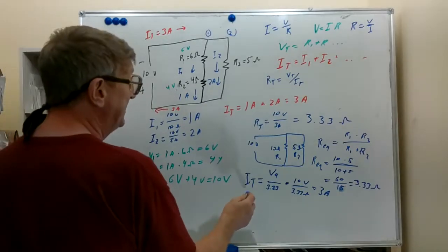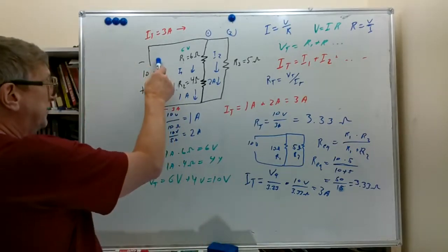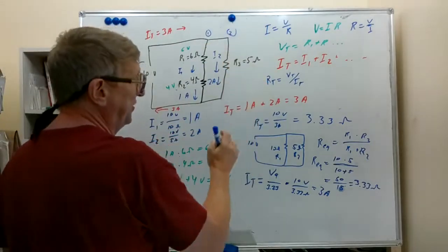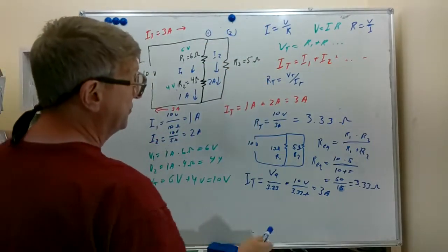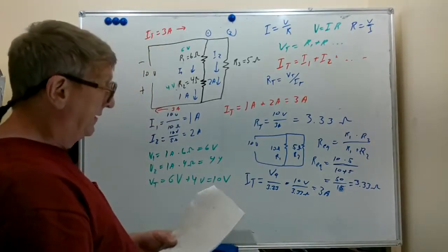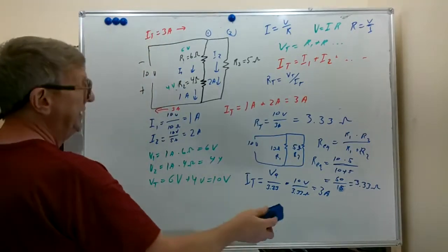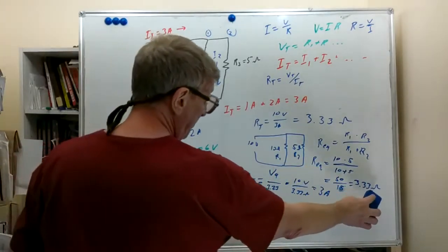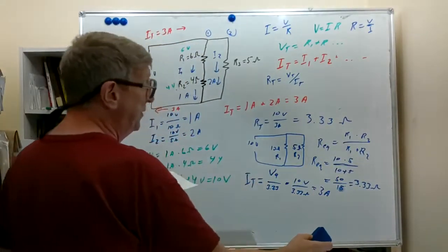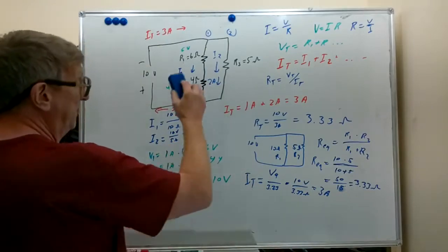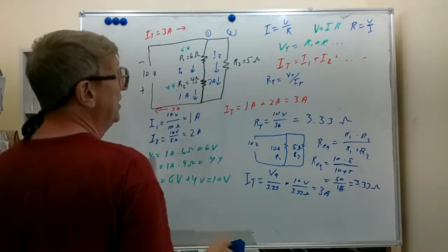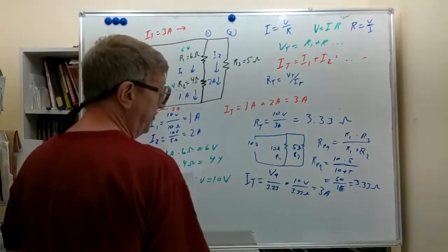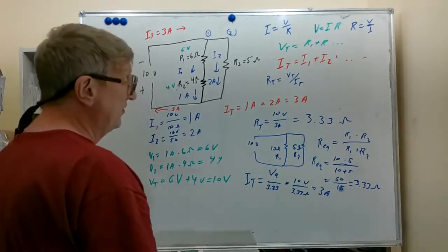But when you want to find IT, looking at the supply, you have to have all of the resistance. If I had another resistor here and I forgot to account for it, this would not give me a correct answer. But in this case, we utilized the entire amount of resistance, which we found two ways. One by solving for the current and using the voltage. The other by doing the series resistance to 10 and then the parallel resistor formula for two parallel resistors.